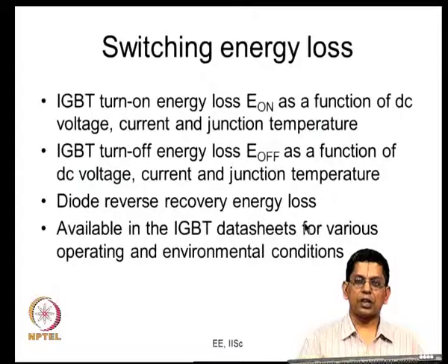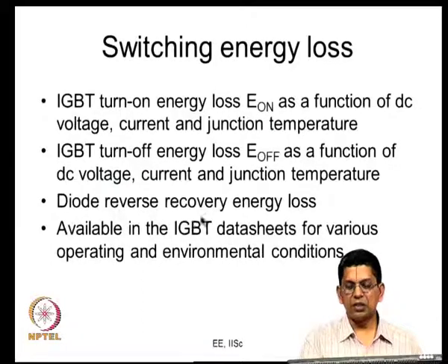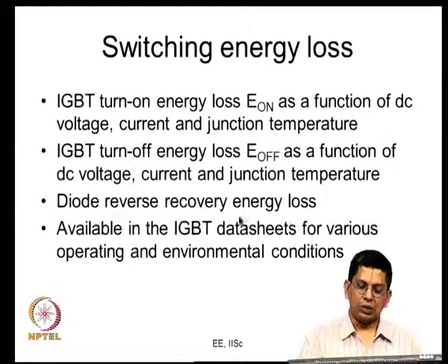You not only have the IGBTs, you also have the anti-parallel diode, and every time the diode is turning off, there is what is called a reverse recovery process in that. So there is a certain amount of energy loss associated with that. So this loss is also known. I mean, all these we need to get from the IGBT data sheets.